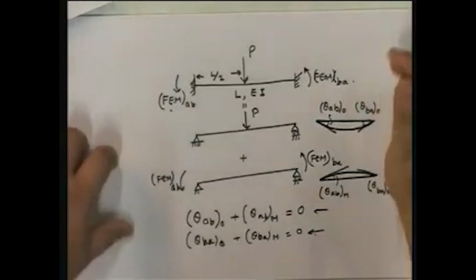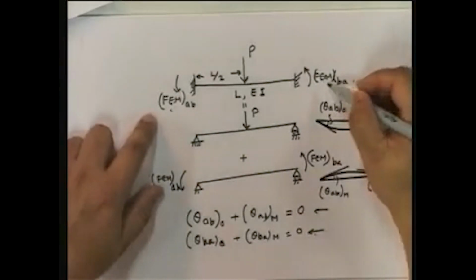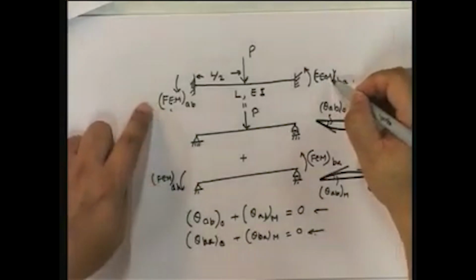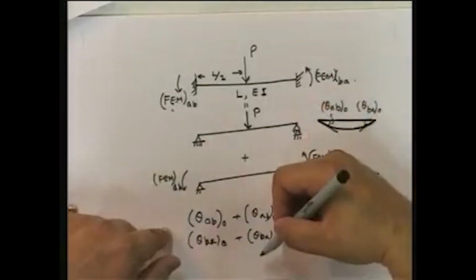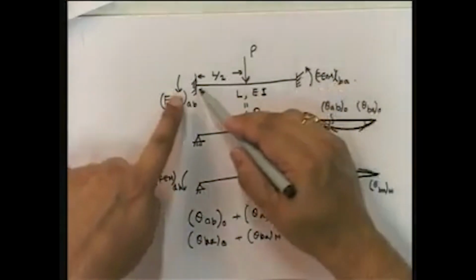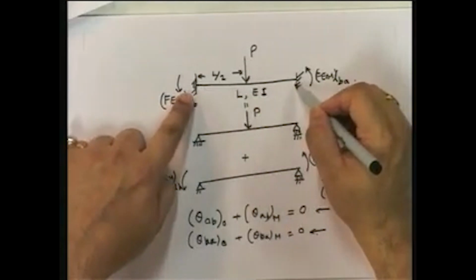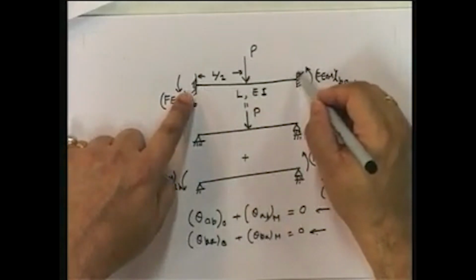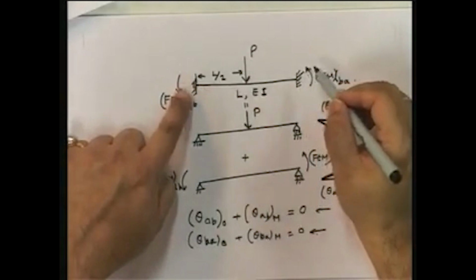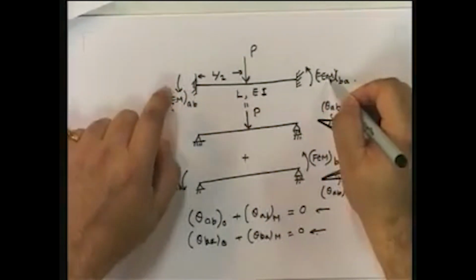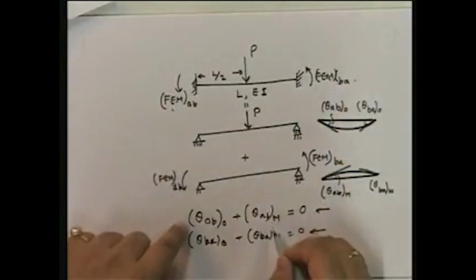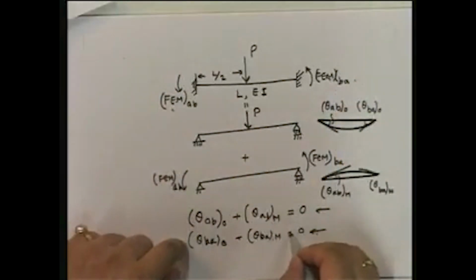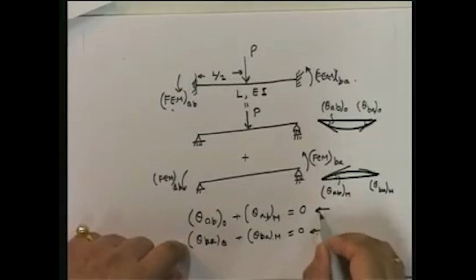So, you see what I am trying to find out? I am trying to actually find out the fixed end moment using the force method. It is very interesting that I am using the force method to solve, because if you look at this, how many redundant forces do you have in this particular case? These two. So, since you have these two as the redundant forces, I am actually writing down compatibility equations corresponding to this.